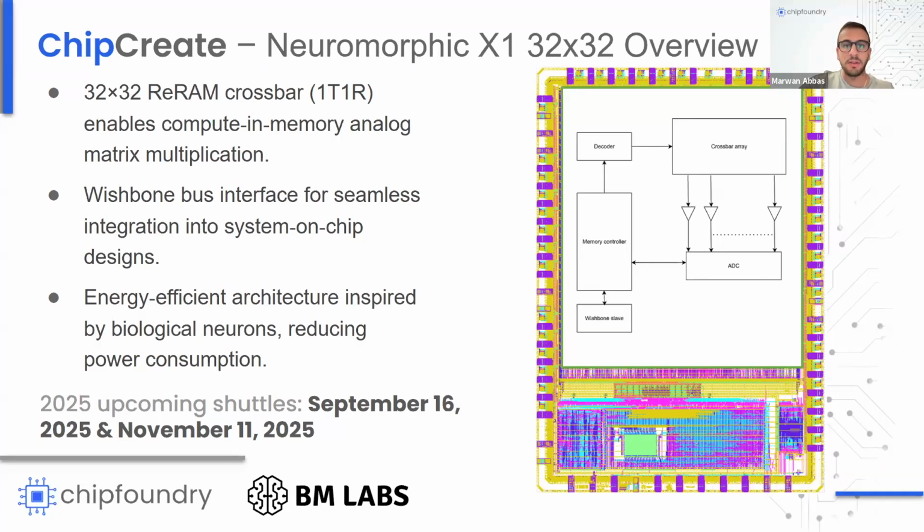How to change the cells? We want to fill the read FIFO without issuing the Wishbone write on that cell. Specify which cell in the crossbar we want to read, because the read address is fixed. So that read address is actually the one I showed, 3 followed by 60 and C, the 32-bit. That's a slave address. That's not the cell address. The cell address is sent in the Wishbone data line.